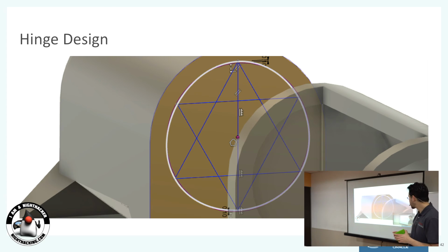So a design like this works better for plastic material, because rather than having a hard edge, which will rub off eventually, it stretches the plastic when it moves, right? It's going to make the hinge material stretch slightly to accommodate the motion. And plastic is a fairly flexible material, so it'll return back to the original shape.